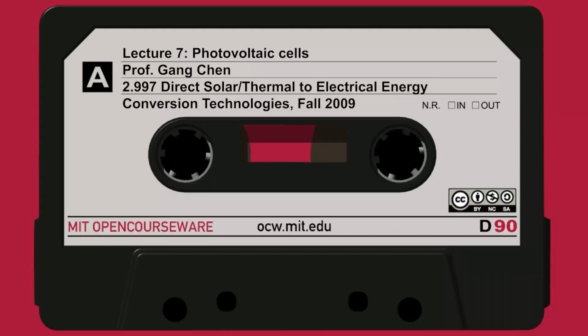Right. And you can see here, P plus, to try to make an ohmic contact, reducing that Schottky barrier. And you have a top electrode, a metal grid. That's a shadow effect. With the metal grid, the photons don't get through. That's not good. So sometimes people even bury the grid down or make it on the backside through vias. So there are a lot of nitty-gritty improvements, a little bit of improvement we put in over the years.